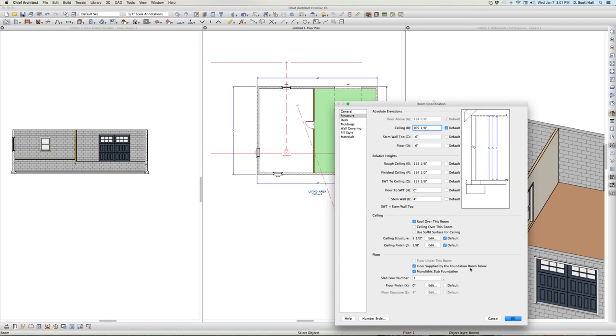What happens there is the elevation of the slab is dependent upon the height of the footing, the elevation of the footing. And remember I said I want the slab to be independent of the footing? I might want the footing to be 80 feet deep, but I want the slab at 0 elevation. I might want the footing to be 80 foot deep, but I want the slab at a certain elevation. So this is what this is all about. You've got to really understand this.